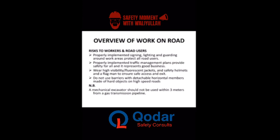Also, when working on road construction, we need to implement very good lighting. We also need to have a very good traffic management plan. If possible, have someone who is in charge. Or if that will be the case, we liaise with local authorities to help us carry out these tasks. We also would not want to use barriers that will be so hard on road users.